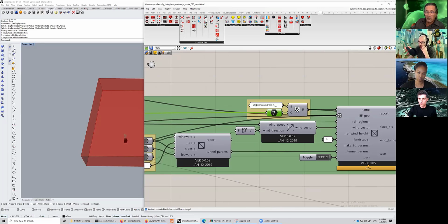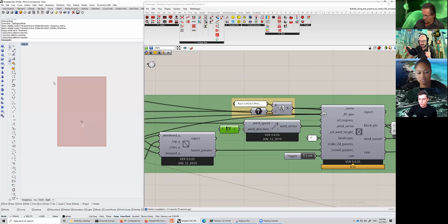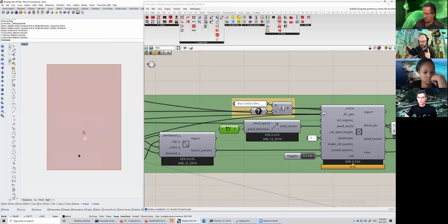So that you create a new name. That's the whole idea. And lastly, we put a wind vector here, a wind velocity, right? As I said, I always use Y+, so it always goes upwards here. It always goes from down to top. You can change this, but at your own peril in the script, right? It's a bit hard-coded right now. And the wind speed, of course, is the appropriate wind speed from the weather file. So this always needs to be here, right?